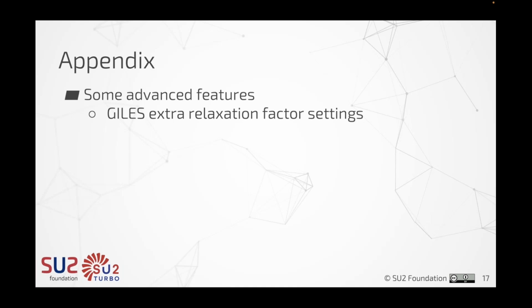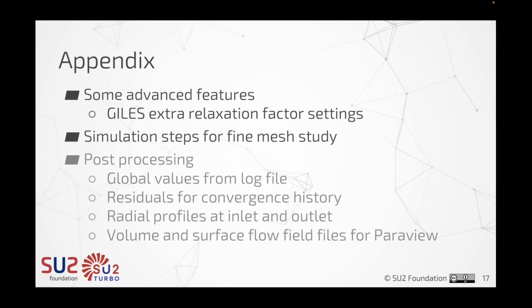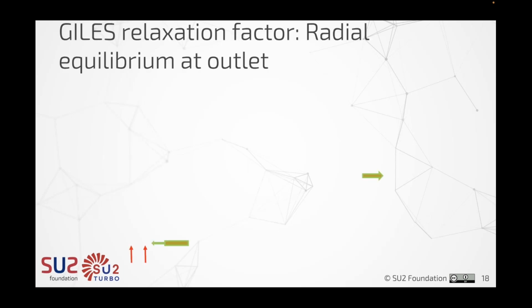So this is some extra stuff that I would like to talk about, the Gill's extra relaxation factor settings, and then the simulation steps, the fine mesh study, because the fine mesh will be available on the portal for people to download and build their own isolines, and some overview of the post-processing.